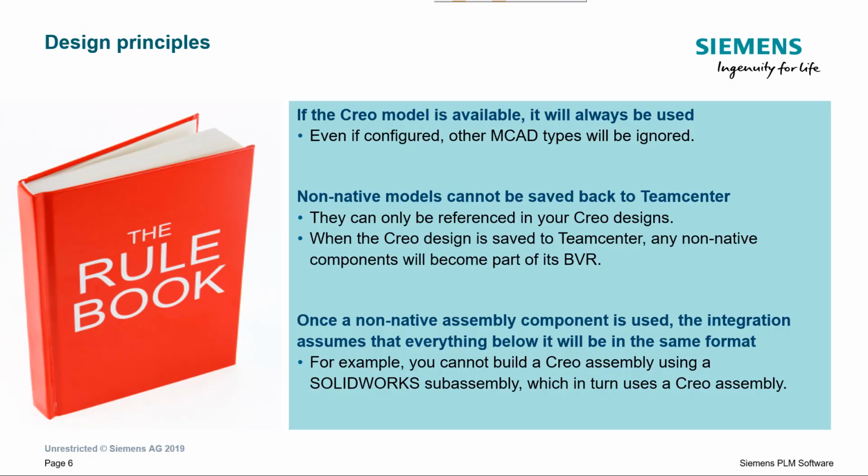Several rules are observed by the Teamcenter Creo integration, when working with non-native design data. First, if a native Creo model is found, it will always be used. Any other MCAD file, even if configured for reuse, will be ignored. Non-native models that are opened or inserted from Teamcenter cannot be saved back to Teamcenter as Creo models. This preserves their identity and avoids duplication of designs under different CAD formats. Finally, nested reuse cannot be supported. Non-native assemblies of any depth may be inserted into Creo parent assemblies, but they themselves must not contain any non-native children.